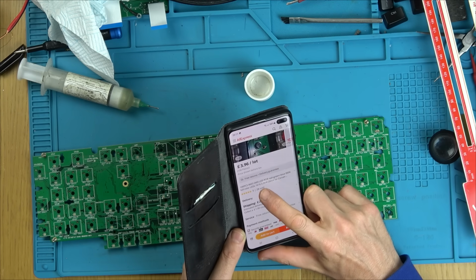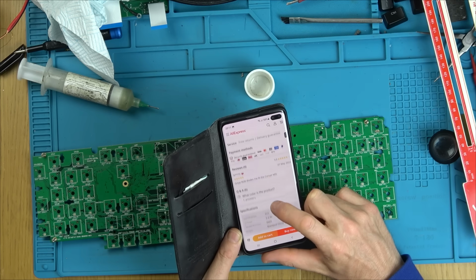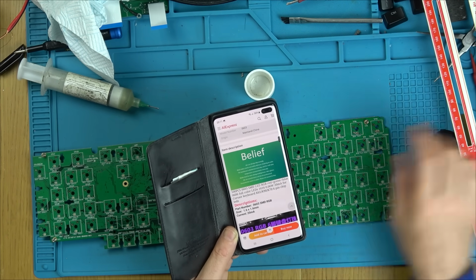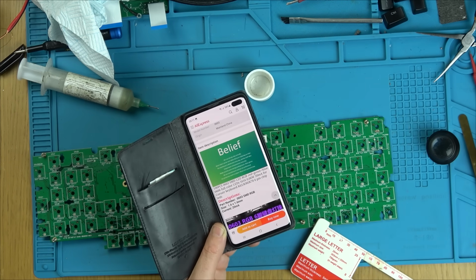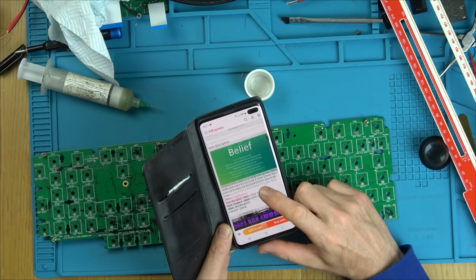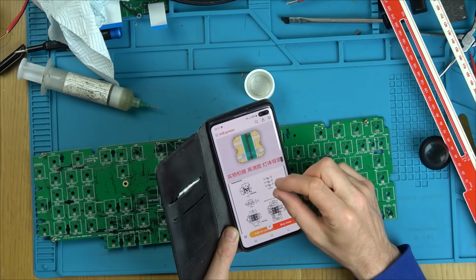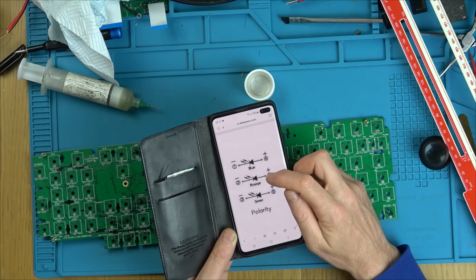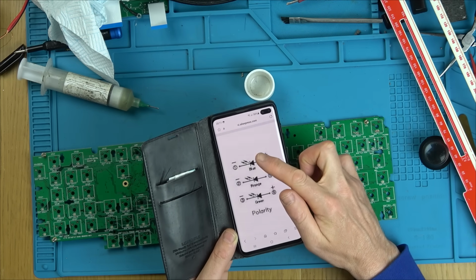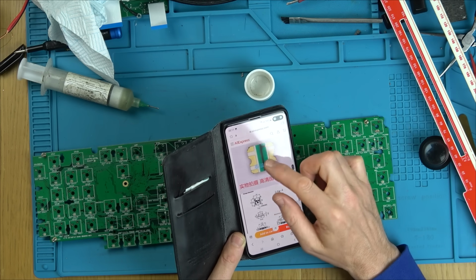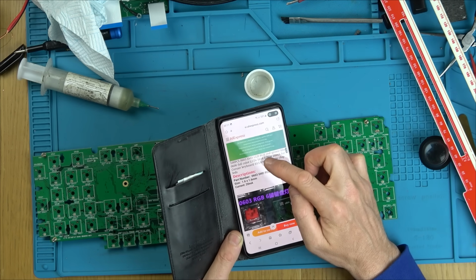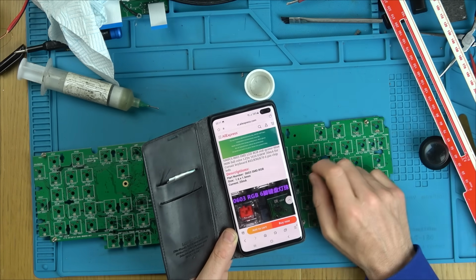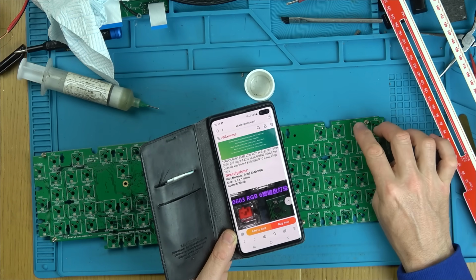And it says here that they're 1616. I was wondering what that means. And look. It says here 1.6 mil by 1.6 mil, and they do seem to be roughly that size here. A bit hard to tell on this one here. And when I actually go down onto it, it has the polarity here, and we know on our one that the red is in the middle, green's at the bottom, and blue's up top. And look, it's the same here, apart from this says like orange but with an R. But yeah, I think they are the same ones. And if you actually look, it says that is for the K70 Corsair keyboards, K70 6-pin. So I'm going to order some of these up. Yes, it's going to take a few weeks to arrive, but when they do, I can start putting them on.